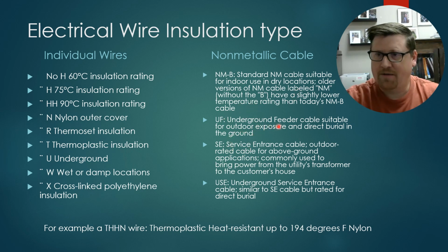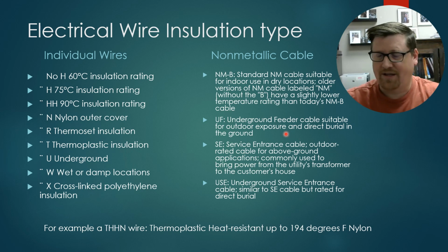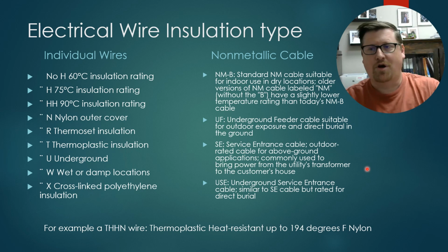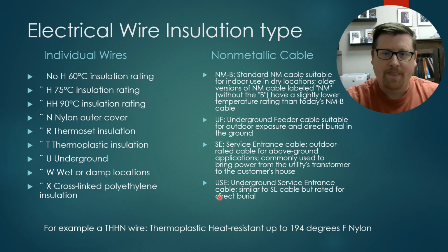UF, underground feeder cable, right? This is good for direct burial, right? So if you needed to run a receptacle out in the middle of your yard or wanted to have a lamp post out there somewhere, you can direct bury this wire as long as you follow all the rules on how deep to bury it. SE, service entrance cable, right? So that's going to have all the wires that you need bundled together in a single cable to run into your main panel for the house. And then USE is that same thing, but you got the U, tells you it's rated for underground, right?